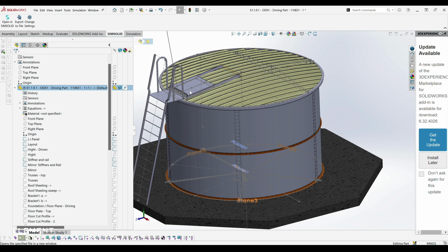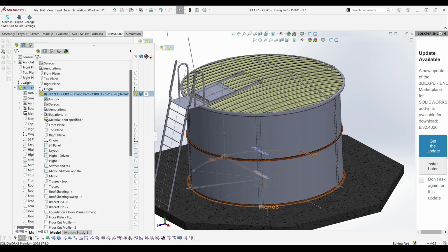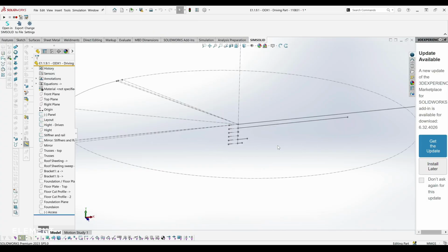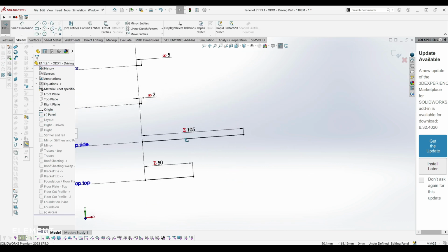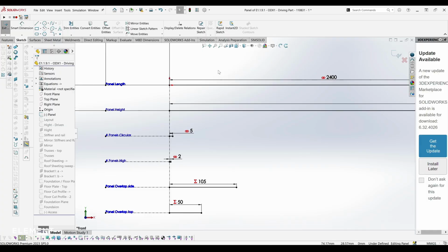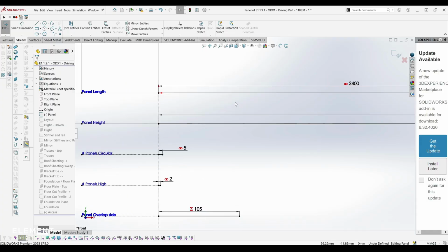This is from 2010-ish or 2012, something like that, when you first started, Dan. It took us a while, but basically you create a top-down model which defines the overall geometry, so you can see there's different diameters, there's different parameters that we've put in there, and they're all driven. So one of them might be the panel length, one the panel width, number of panels high, panels low. You can basically use these drivers as an input to then generate a whole model. So using the same standard panel sizes with standard bolt patterns, you can make an infinite number up to a certain size of these things.